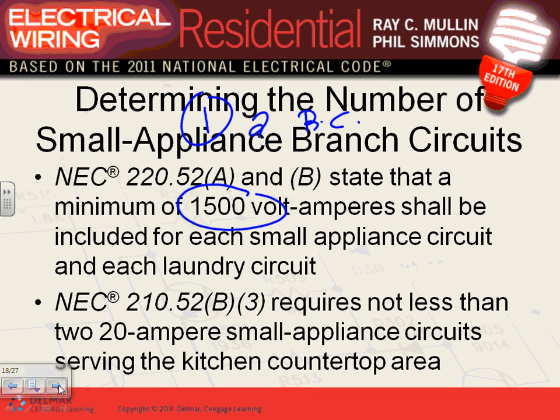What I've done when I wire them, anybody who wires, we use 12-3. You come to receptacle number one, feed it from circuit one, circuit two, circuit one, circuit two, and you loop it around the whole house. Very easy, shared neutral, done deal. Any questions, guys? So for the kitchen, here's one special case: two circuits for the kitchen.